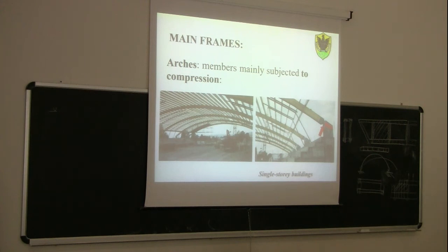Because I just remind you that timber and reinforced concrete have more or less the same strength. So here a structure made of timber would have had more or less the same size. However, the horizontal deflection would be, in case of timber, how many times the one of concrete? Remember, more or less? Not 30%, much more. And yes, let's suppose that we have done the same structure here made of timber. So, a structure like this made of timber, first of all, which size would it be? In terms of strength, how would be the cross section? Larger, smaller, or the same? More or less the same. Because if you remember, the strength is more or less the same.